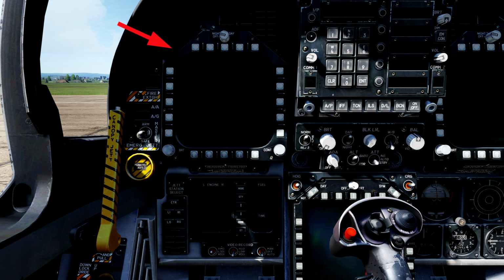And to the right of that is your multi-purpose display indicator, or your MDI, and these replace the older DDIs from earlier lot Hornets. Now here above your left MDI is your left engine fire indicator, your master caution light, as well as your left instrument advisory lights. And here below the left MDI you have your selectors for selective jettison for center and the left and right wing stations, and below those you have your indicator lights for your landing gear and flap positions.